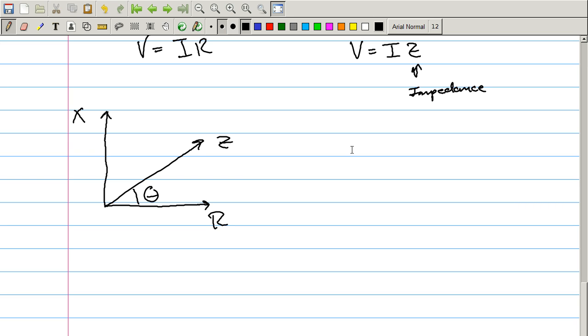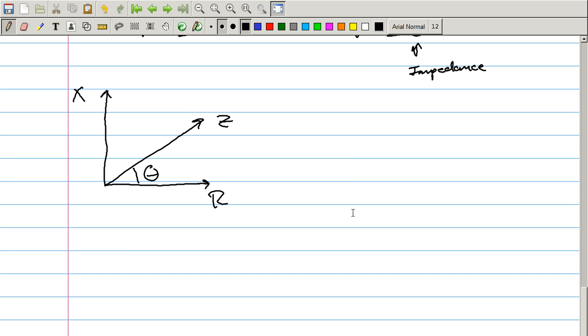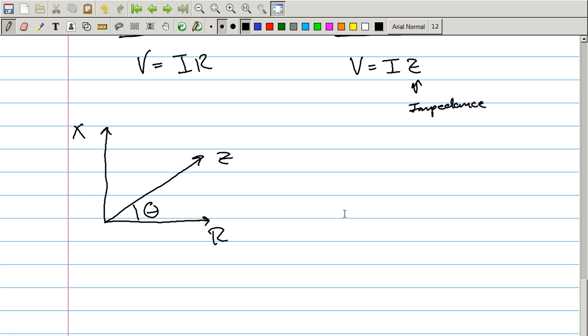So, in AC there is an element of resistance. A resistor has an impedance R. It has no reactance. You can think of this as two things. Resistance is just magnitude. All it does is reduce the current through the system. Impedance is a combination of just that resistance and also a time-dependent component, that phase shift. What reactance does is it doesn't change the amount of current, it changes the phase of current with voltage. Again, AC is a time-dependent system, so phase is a factor.